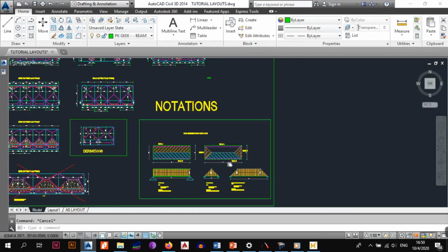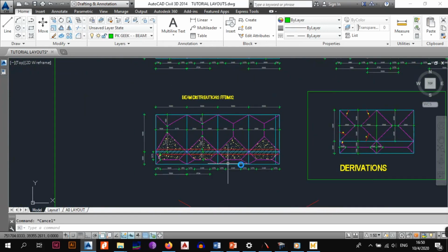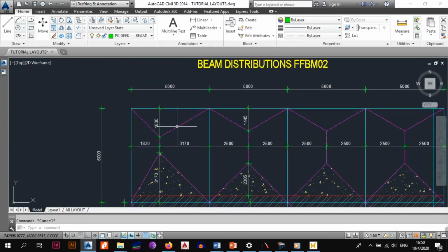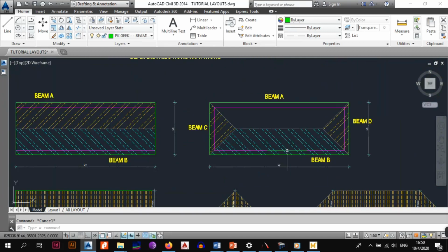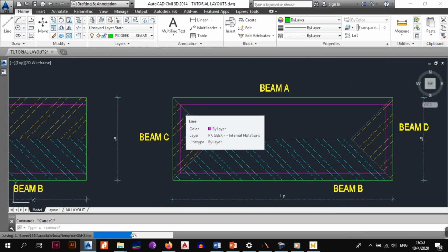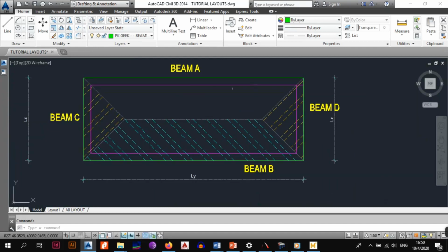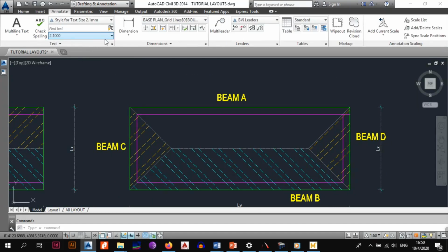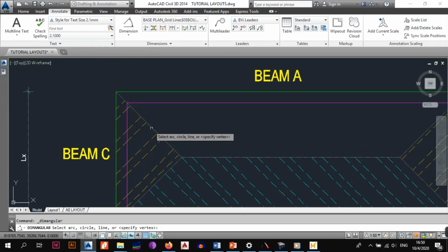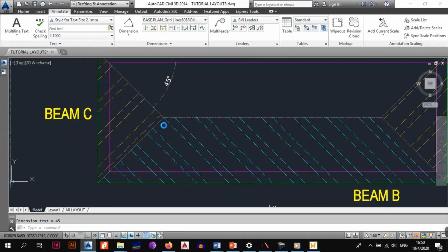So whenever you have your structure or your shell, in this case with our layout, what we had to do is come up with a shell, and then construct these lines. Some people will be asking me, how do you construct these lines that show you that the area is the one given by the shade, which is in orange? It is easy. When you have a simple slab like this, the theory just says all you have to do is create a 45-degree line, then another 45-degree line. This is from the shorter side. This is what you do.